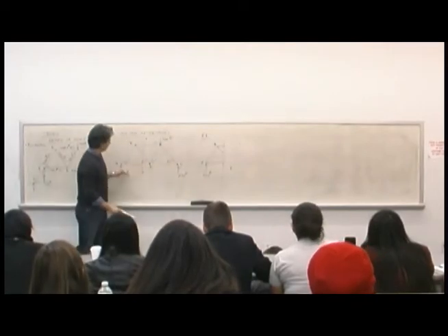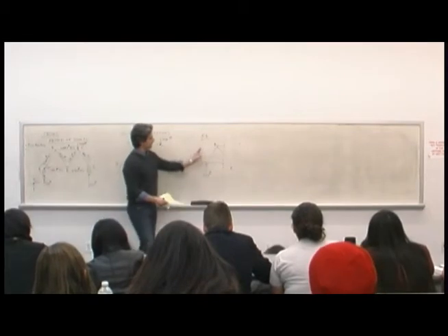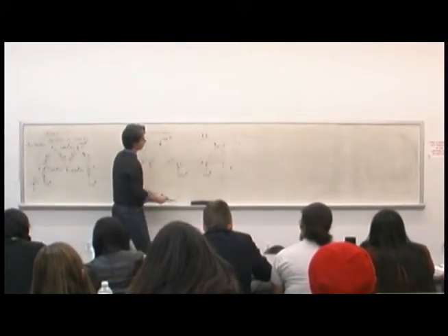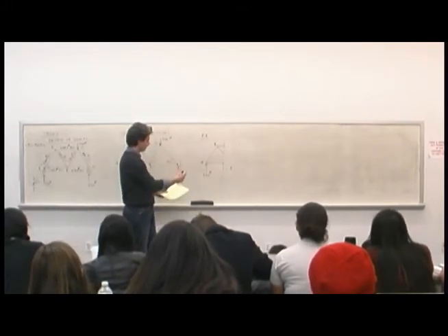I'm assuming we found the reactions, right? Same way we did it the first time. I take this portion of the truss and I imagine cutting through the members and exposing the forces.